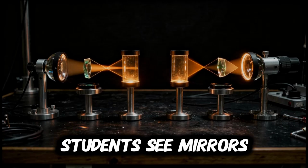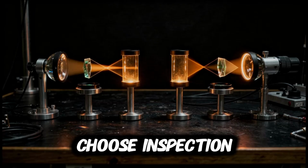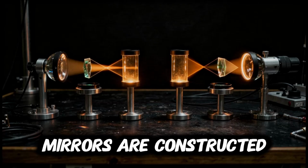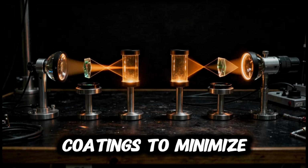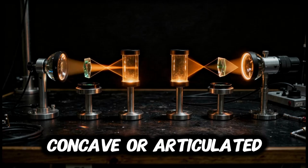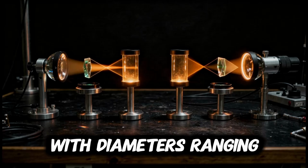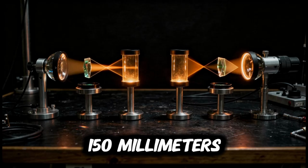Students see mirrors, borescopes, endoscopes. How do we choose? Inspection mirrors are constructed with first surface aluminum or dielectric coatings to minimize double imaging. They are available in flat, concave, or articulated configurations, with diameters ranging from 25 to 150 millimeters.